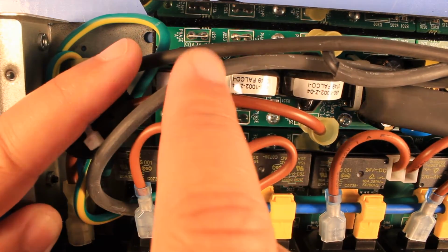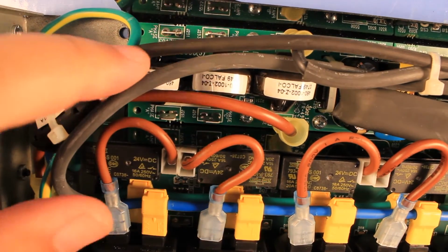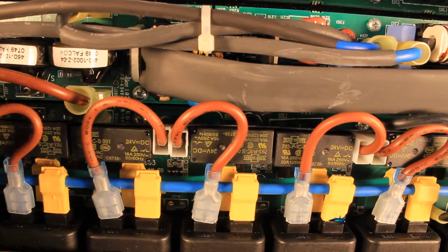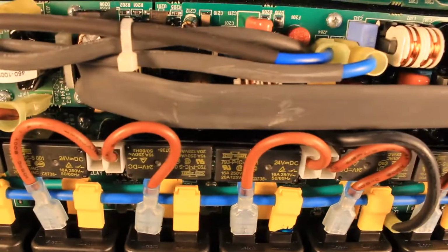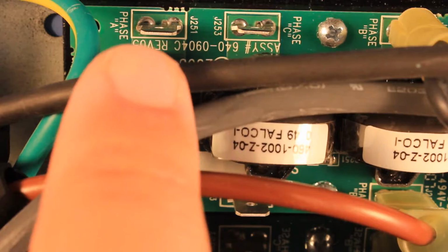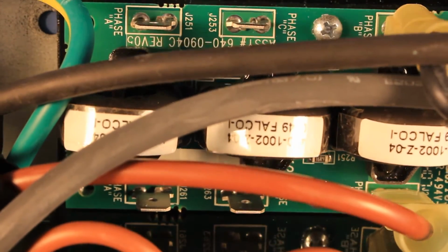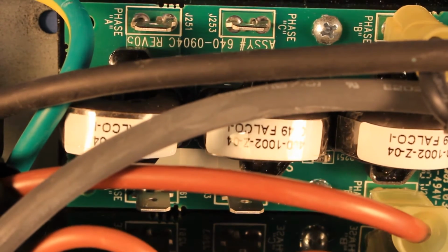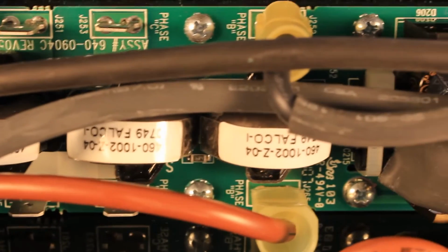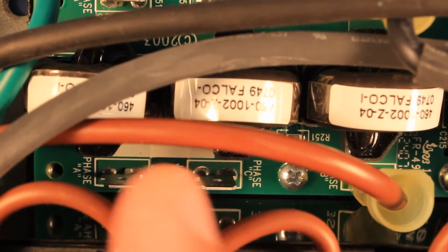Here this upper PCB is the one which is holding the transformers for the current measurement. Then here are some AC to DC switch mode power supplies. Here we can clearly notice that this PCB is a pretty standard PCB apparently for these APC power distribution units, because you can notice that there are actually three phases present on the board.